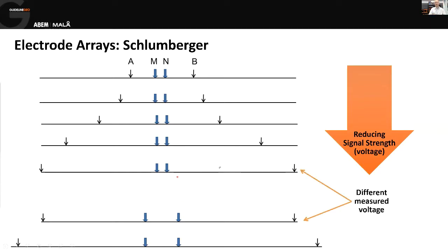But that gives us a little problem as well, because that means that for the same current electrode spacing, which is giving us a focus point at a particular depth, we've now got 2 different voltage measurements. So when we come to do the processing, we need to normalize those. We need to bring the second set of data with the new position for the voltage electrodes up to meet our original data set. And so we make sure that we repeat this reading. So you see the same current pair is repeated so that we can compare the difference between the 2 sets of data. And if we want to do it properly, we actually overlap by 2 or 3 readings.